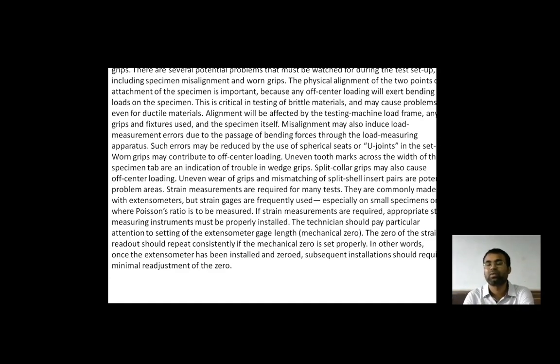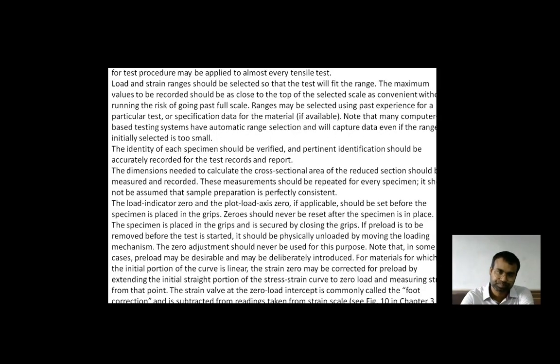So in other words, once the extensometer has been installed and zeroed, the subsequent installation should require minimum readjustment of that zero, and then when the load is applied on the material by the test, that can be measured by this extensometer.